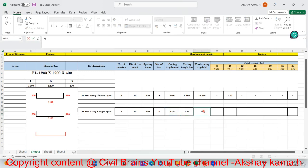Now coming to the total cutting length. This also remains same. That is cutting length of one bar multiply by number of bar multiply by number of members. Close the bracket. Finish. 13.140. This you can increase the number. So again, it's a 10 diameter bar, no? So come here, plus open bracket, total cutting length of one bar. You multiply this, I mean, total cutting length multiply by the unit weight of 10 die, which is 0.617, and close the bracket, hit the enter button. So you got 8.11. Okay, finish. That's it.